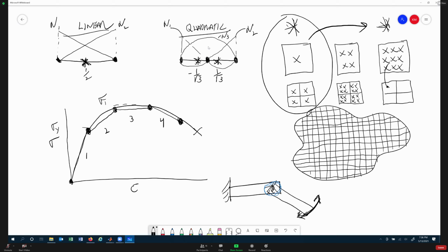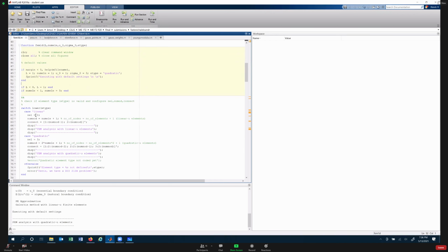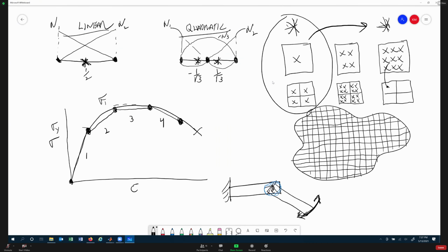And I always think of it almost like spending money, right? You start off super cheap, you try it out. Am I going to like this? And then you add more complexity or more detail as you need to. Because if you get into work and you jump right into really high order element types, really high density, and you're trying to troubleshoot your model, it's kind of like trying to troubleshoot this MATLAB code. You have to start with a single couple of lines at a time. You run it, you check it against something you've done by hand. It's really the same thing. You're decoding your finite element work to make sure that you've set it up right and you have everything working cohesively like you planned.